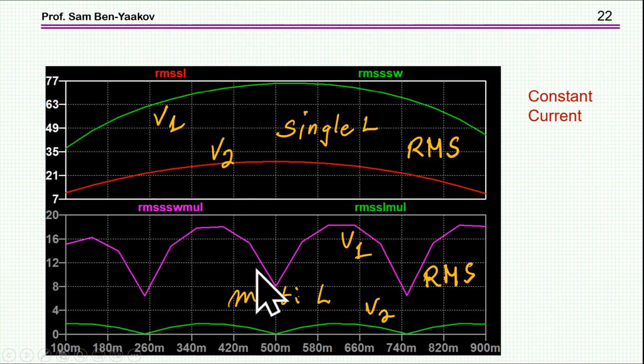This is the V1 side, like the input of the buck or output of the boost. And here I see the output side of the buck. I see here very nicely the 0. I have 4 inductors, so I have 4 portions here, 0.25 duty cycle apart. And this is for the full run with the numbers that I have for the input voltage, the current, the load, etc.